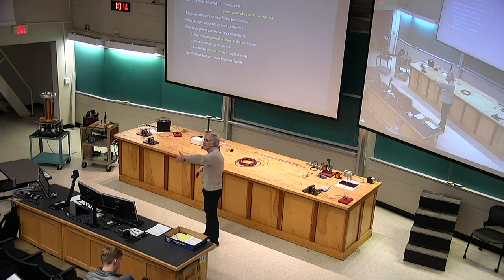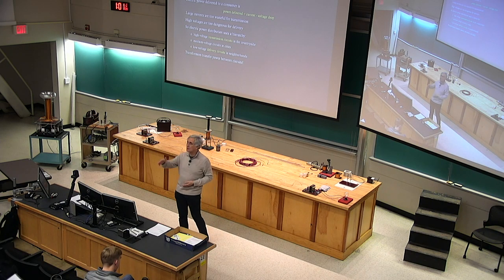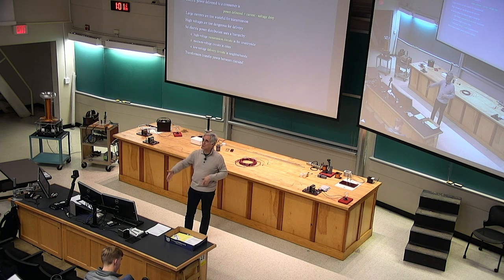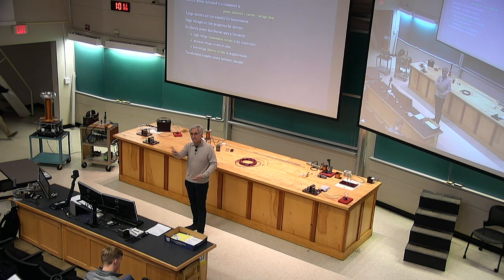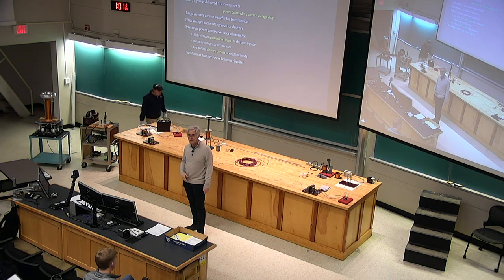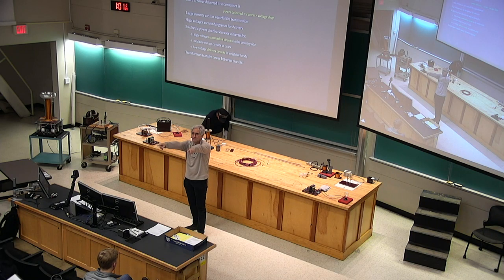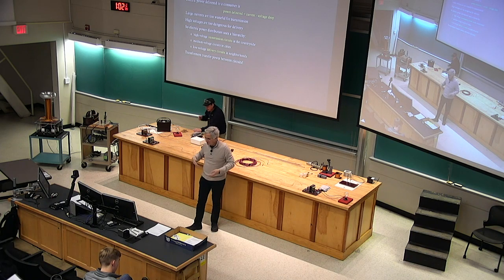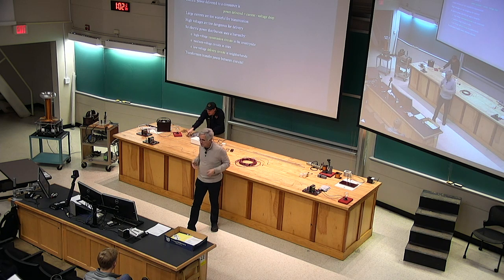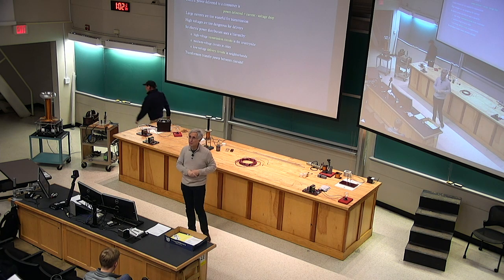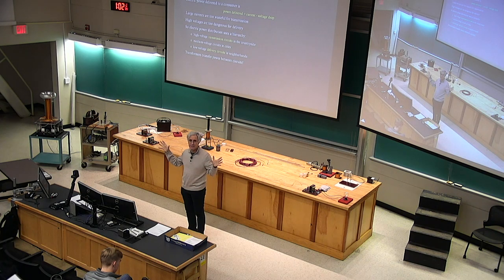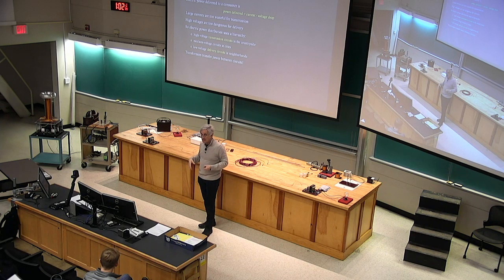The user takes the energy, returns the charges to you as a large current at a somewhat smaller voltage than it arrived in, having had energy taken out of the charges. So that's one delivery approach. Large current, small voltage difference between the current that arrives and the current that departs from the user. Any questions, issues about that idea? Large current, small voltage, it's okay? The product of the current flowing times the voltage drop at the user is the power that's delivered.